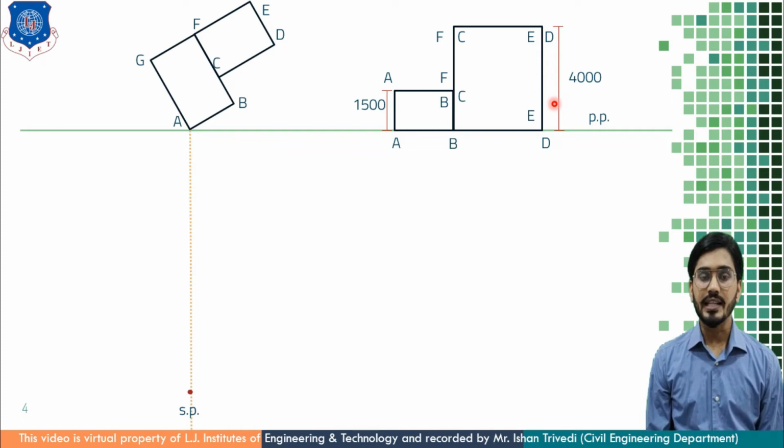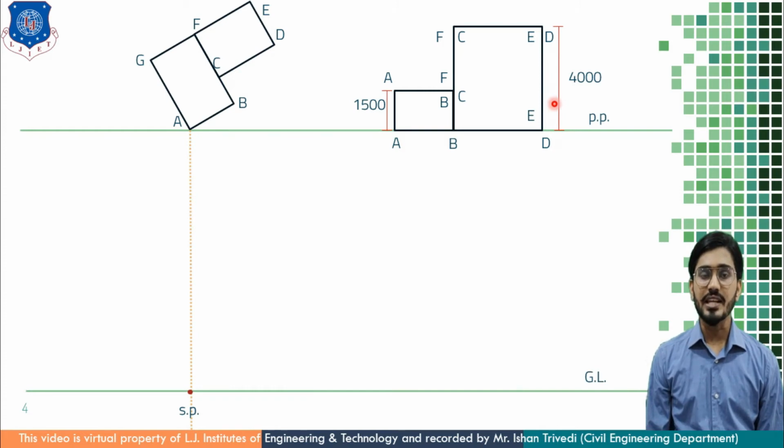Then, as I said, as AB makes an angle of 30 degrees to the picture plane, a parallel line is plotted for the AB face and CD face. In the previous session, the SP, VP and ground line were separate. But in this session, I am putting SP, or station point, on the ground line.